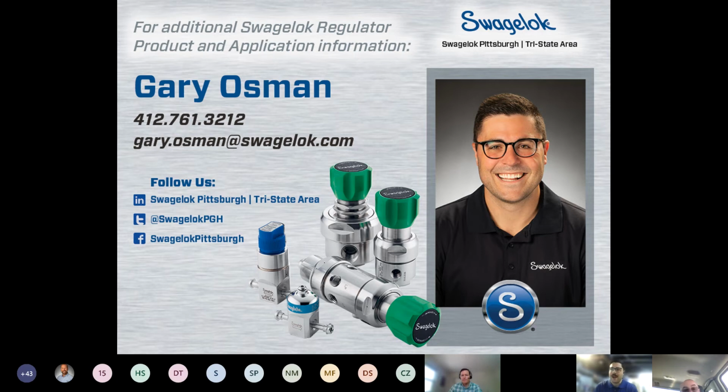This one's related to the venting. The question is, is self or captured venting usually incorporated in single stage as well or only two stage? The way we saw it in the presentation, that was single stage regulation when you had the cutaways showing the venting options. Yes, you can have self or captured vents in both single and dual stage regulators. Everything we saw in the cutaways was a single stage regulator to show the venting options, but they can be incorporated in a two stage as well.